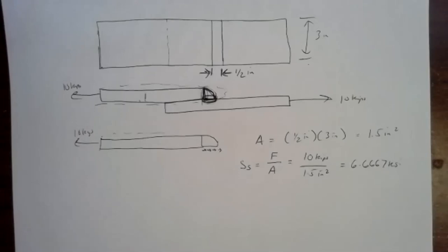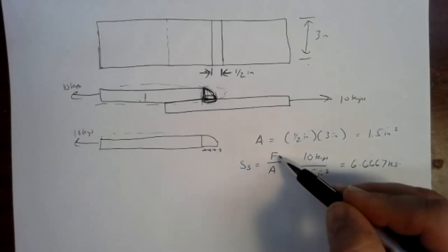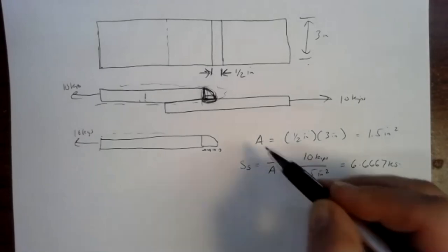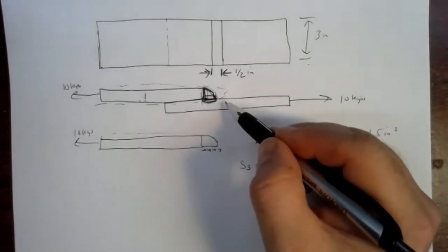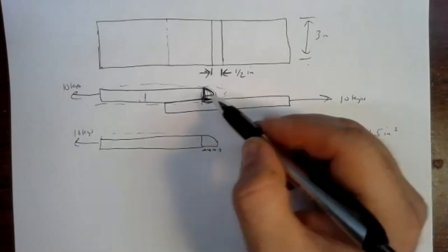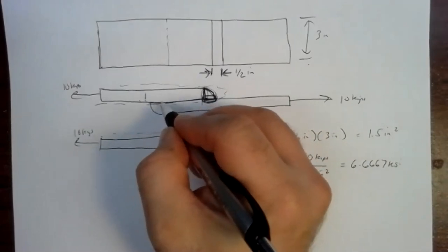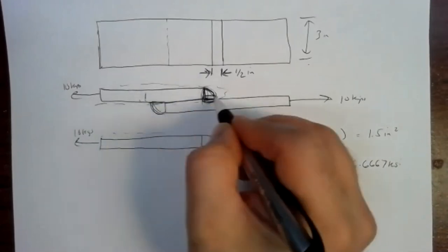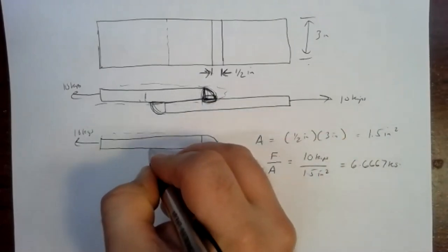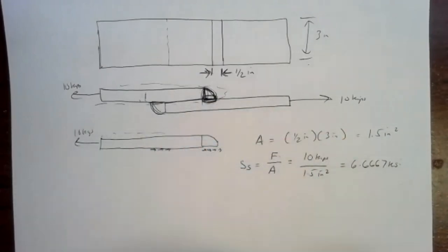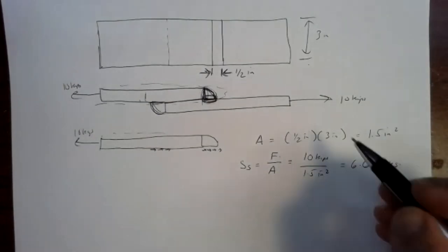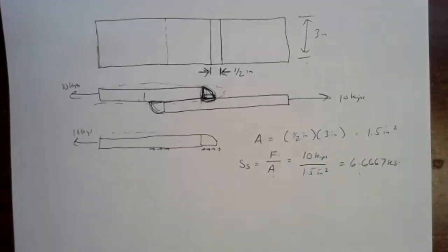Now, for some reason, if we figured that stress is too much, we could change things. We could change the force, or we could change the area. We could, in principle, make this a bigger weld, or we could add another weld. We could do a double lap joint where we put another weld down here. If it's the same basic size of that weld, then we've got two areas where forces are applied, and we would effectively double the area. If we double the area, we cut the stress in half. So we go to 3 square inches of area and then 3 1/3 KSI.